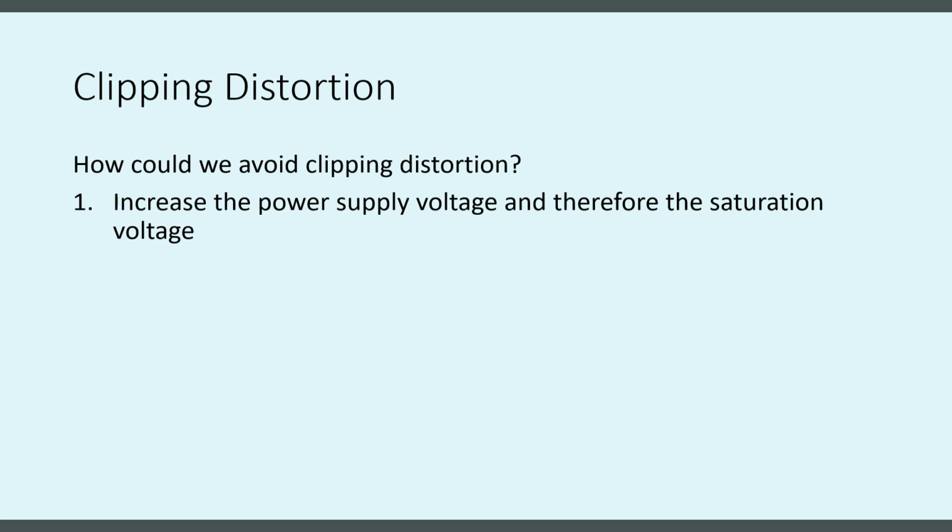Bear in mind that 1 or 2 volts is usually lost, as op amps aren't ideal, so you're probably looking at maybe aiming for 18 volts or possibly going up to 20 volts to be on the safe side.